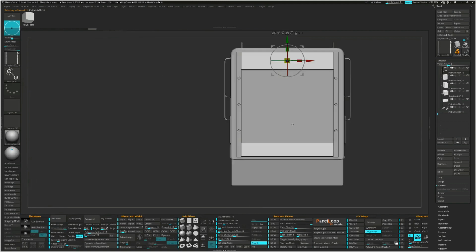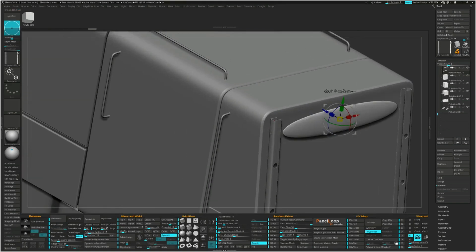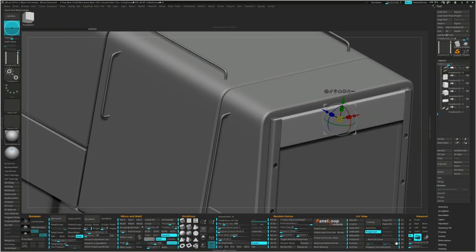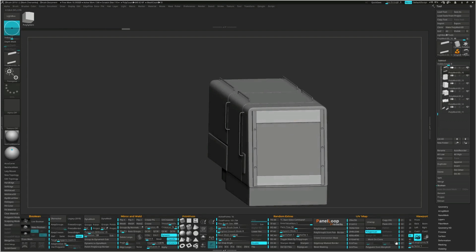KeyShot has a cool rounded corners feature, so you can turn off dynamic on some pieces and have KeyShot round the edges. It will depend on the shape of your object and how the textures from Substance are reacting to it. Another strategy is to model with dynamic off. Build the edges in to capture the form, then when you send it to KeyShot, you can smooth the normals by an angle and have a much lower poly count.